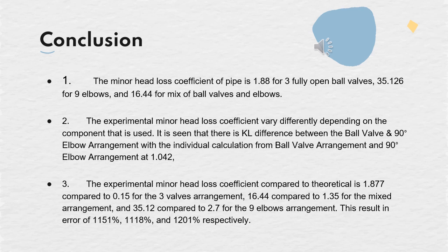Second, it shows that the minor head loss coefficient can vary between the components used, in this case ball valves and elbows. And it can also be seen that the value of KL from the first and third experiment differs from the second experiment when calculated, which shows that there is further inaccuracy in this experiment.